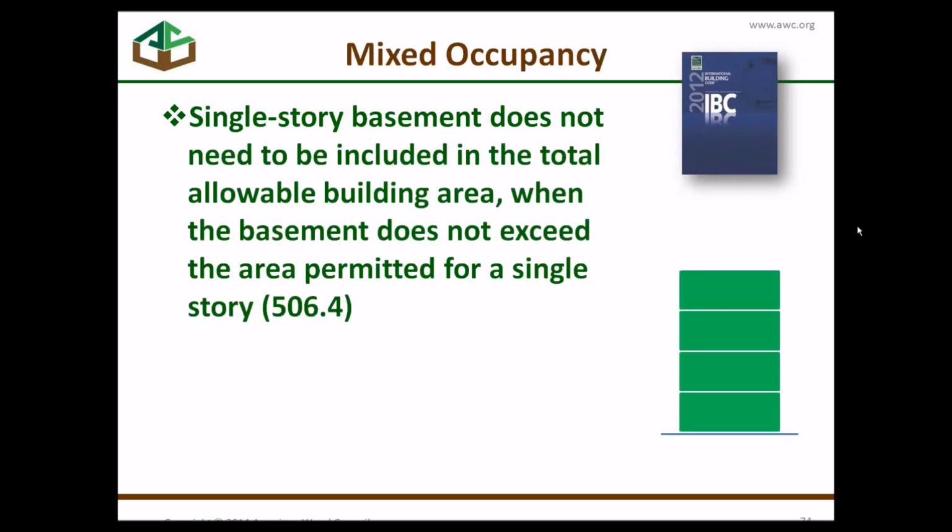Now, you can have a basement. Section 506.4 says you can include a basement, and you don't have to include that in the allowable area of the building. So put a basement on that story there at the bottom.